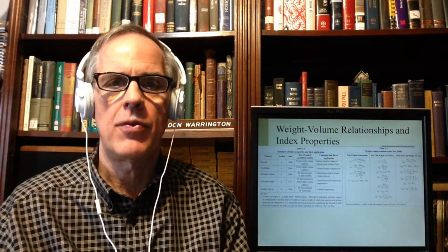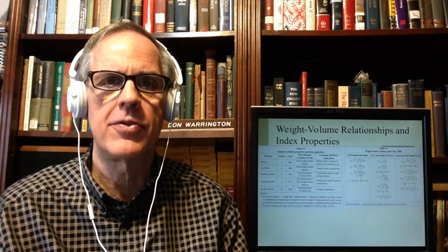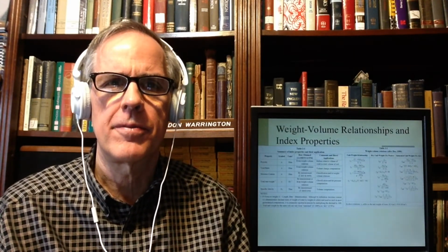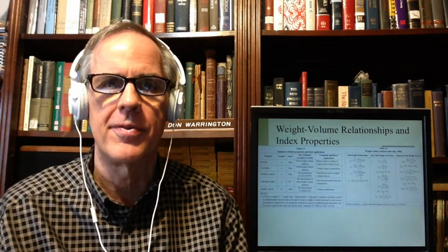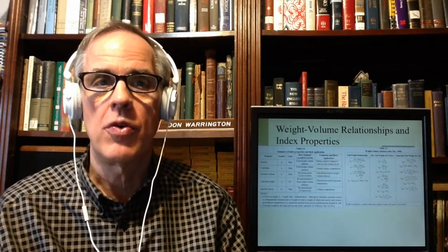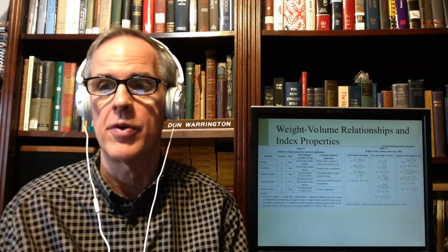And then the dry unit weight is when there's no water, and then the saturated unit weight is when there's no air. Which one of these you use obviously depends on the soil sample. If you have a soil that's completely dry or completely saturated, that simplifies a few things because you don't have to worry about the proportion of the voids being water, soil, or some water and some soil. If it's either all one or all the other, we'll use those two in various ways as we go along.